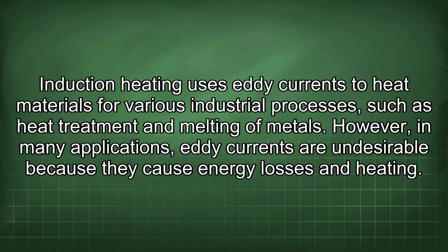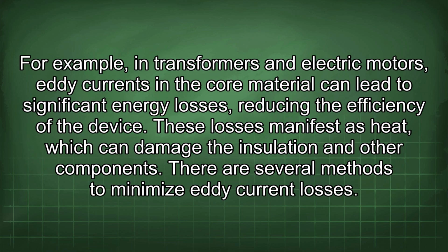However, in many applications, eddy currents are undesirable because they cause energy losses and heating. For example, in transformers and electric motors, eddy currents in the core material can lead to significant energy losses, reducing the efficiency of the device. These losses manifest as heat, which can damage the insulation and other components. There are several methods to minimize eddy current losses.